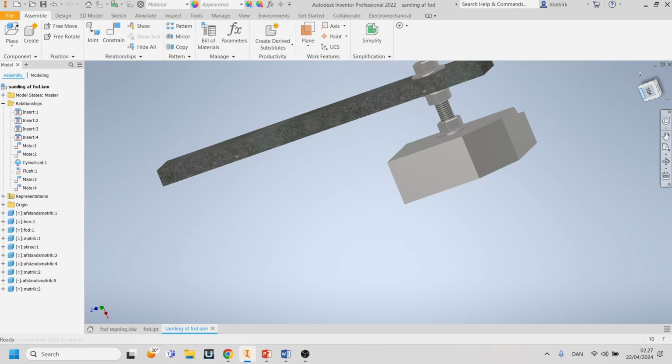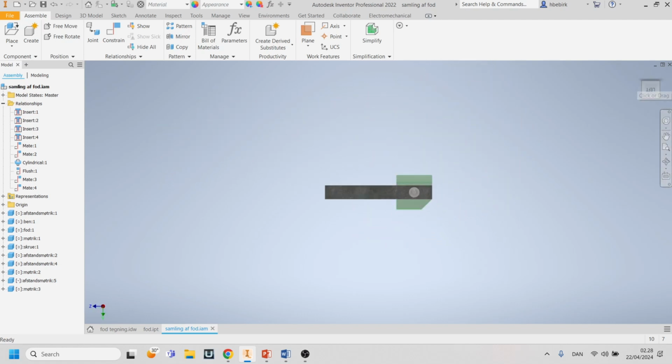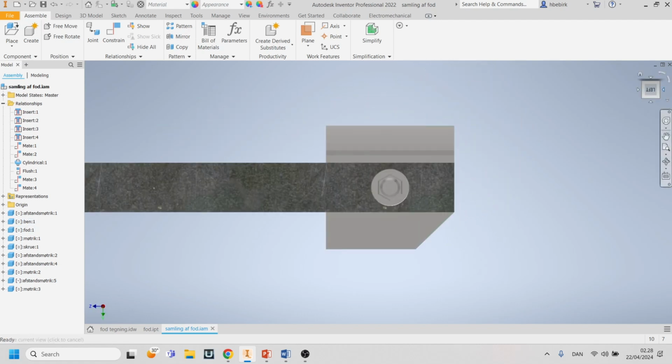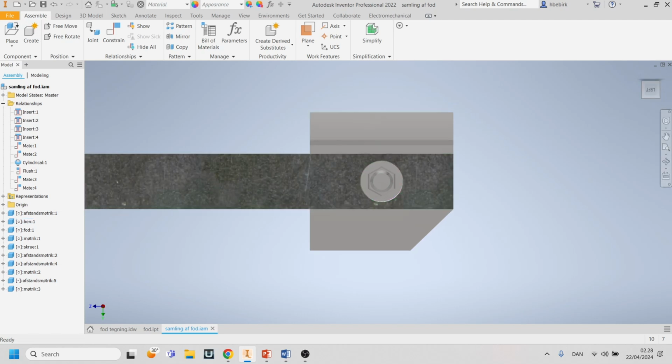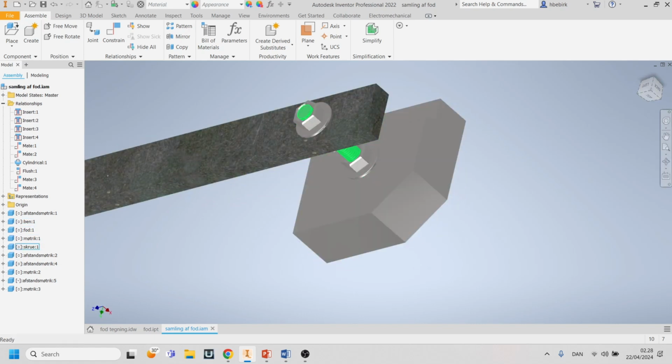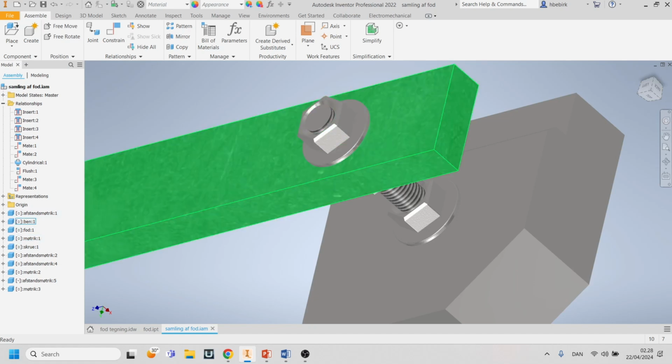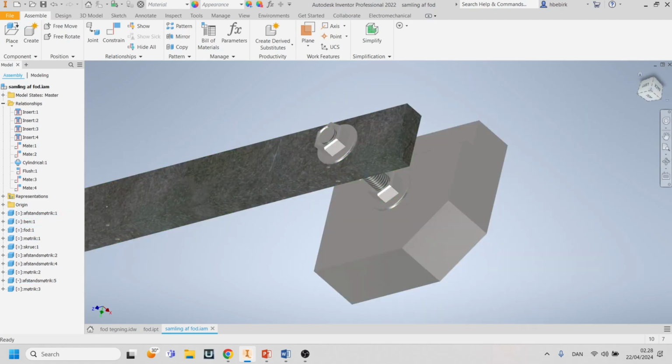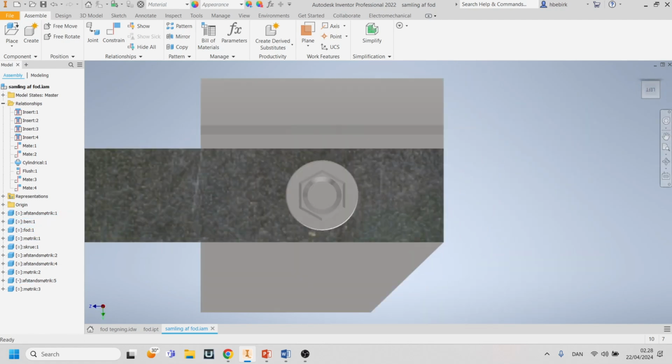It could be a foot, an adjustable foot. And if we go to the top view here, which is left, I drew it in the wrong axis. The faces are completely flush, also flush with the chamfer. And you could say that if this hole was moved on the flat bar steel, which we were talking about, the parallelity on each side and also the symmetry to the hole, well, then this one will not be flush at all and it will stick out.